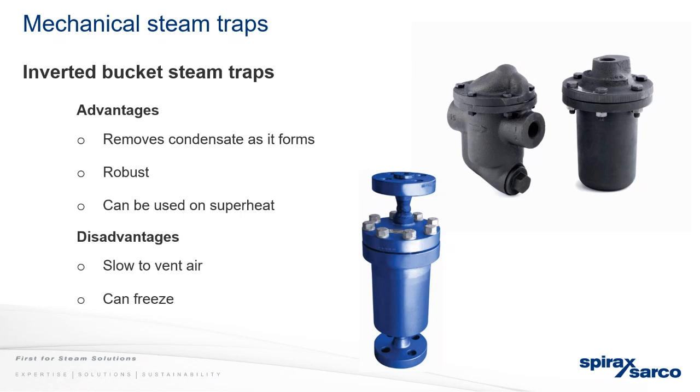Look, the testing is an interesting one. How often do you have to test these things? I think it depends on the type of trap that you've got and the type of application that you've got. For critical applications, I'd say one could go to a more digital thing where we can add a wireless diagnostic kit to a steam trap to at least indicate when the trap has failed closed. And that could continuously monitor the steam trap. And there's various other ways of doing it from a continuous point of view. And you can get a dashboard to actually help you understand what your trap population is doing.